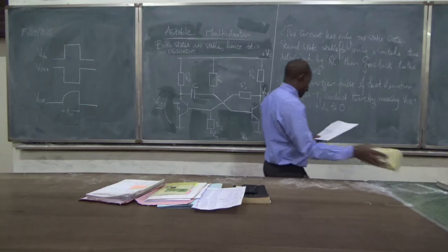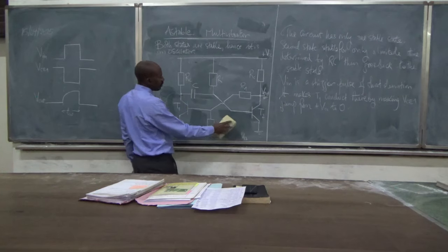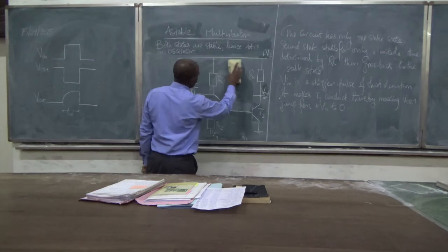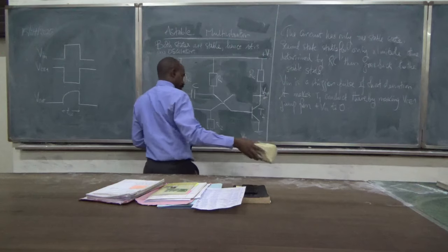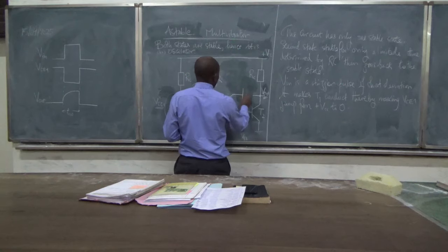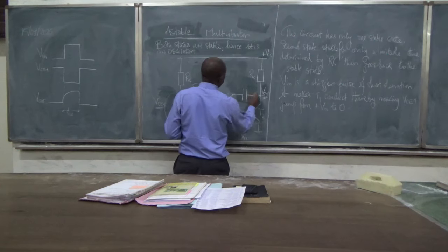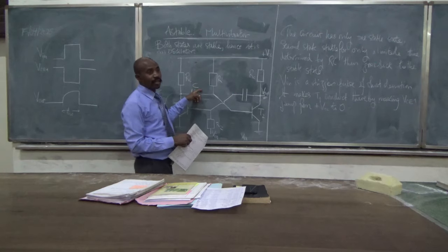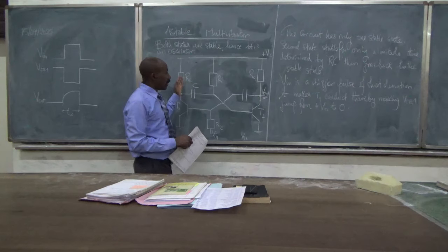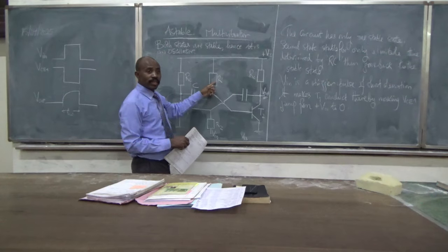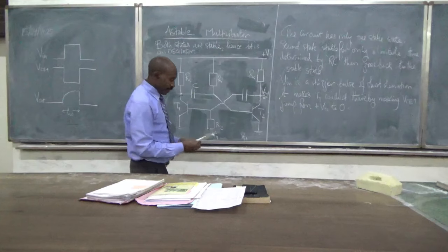And the idea is that we now put this other resistor here and put another capacitor here. So we have the capacitor. RC is the collector resistor. Don't confuse RC with this capacitor. They have nothing to do with each other. It implies that the only resistance connected with the charging of the capacitor is this other resistor.